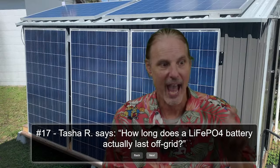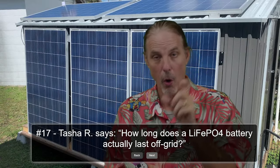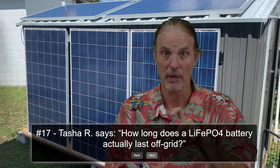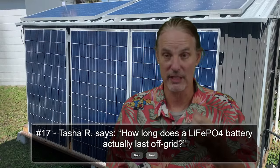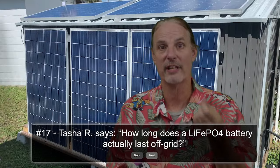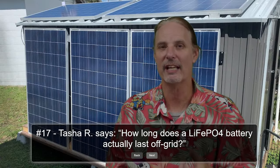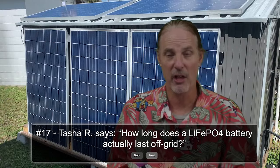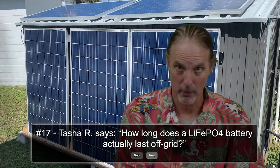So actually, the life of the battery becomes the real question here. Over time, the battery is going to lose some of its capacity. In the case of a JK BMS, or the EG4, which has a lifetime cycles meter, it calculates what they call the state of health. The state of health means that if I'm at 95% state of health, my 100 amp hour battery is now a 95 amp hour battery.